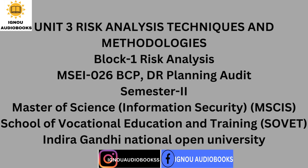Failure mode and effects analysis is a procedure by which each potential failure mode in a system is analyzed to determine its effect on the system and to classify it according to its severity. When the FMEA is extended by a criticality analysis, the technique is then called Failure Mode and Effects Criticality Analysis, FMECA. Failure mode and effects analysis has gained wide acceptance by the aerospace and the military industries. In fact, the technique has adapted itself in other forms such as misuse mode and effects analysis.